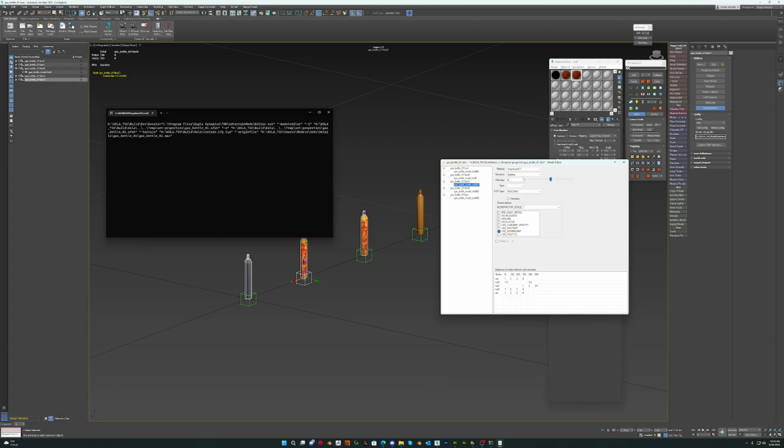We'll go on to the model itself. This needs to be not V-Ray House 5.1, it needs to be V-Ray House LOD 5.1. The semantic is still building, the flare type is still building, the proxy bias needs to be 1 because this is LOD 1, and we turn off the use normal map because at greater than 400 meters, you're just wasting video memory displaying a normal map on something you will never ever see.